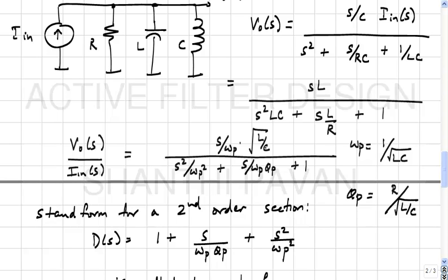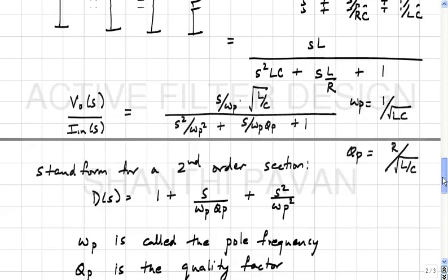One, of course, is when the LC becomes open, the impedance is R. From this expression, when S becomes equal to j omega p, 1 plus S square by omega p square goes away, and the numerator S by omega p cancels off, and you have square root L by C divided by 1 by QP. So QP goes into the numerator, and QP is nothing but R divided by square root L by C. So the impedance must be R. Okay. All right.